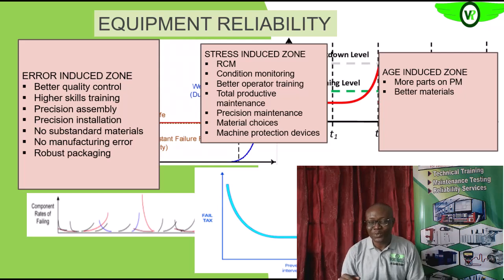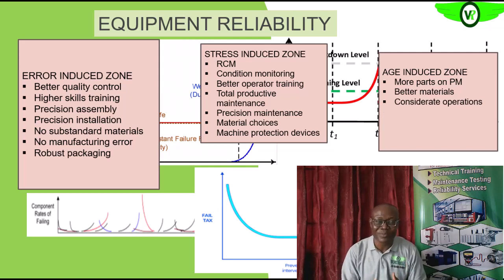Which means we need a higher rating of components to help us withstand that increased failure probability in the equipment. Then of course we want to be considerate when operating the equipment in this region. This is the region where we recommend derating the equipment, subjecting it to lesser stress than it is designed for. So that is one way we can do it.